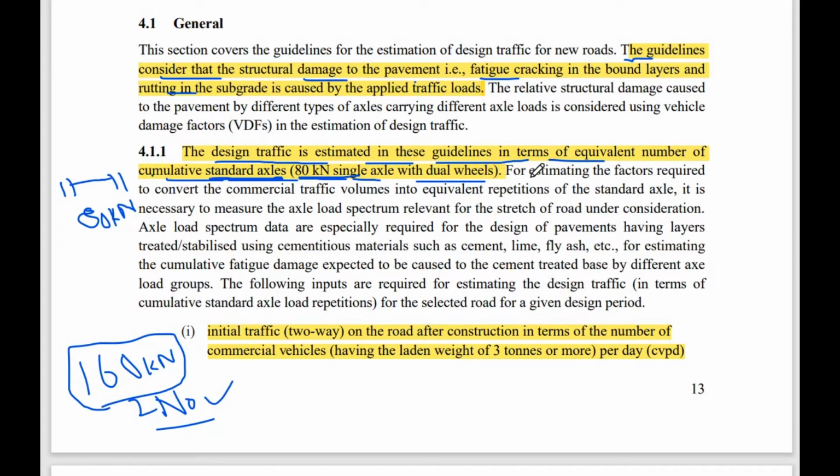Let's move ahead. For estimating the factors required to convert the commercial traffic volumes into equivalent repetitions of standard axle, it is necessary to measure the axle load spectrum relevant for the stretch of the road under consideration. So here they have said that for the conversion of the normal axles into the standard axles, we must measure the axle load spectrum. What is the axle load spectrum? It is the range of the axle loads that our pavement will face in the future.